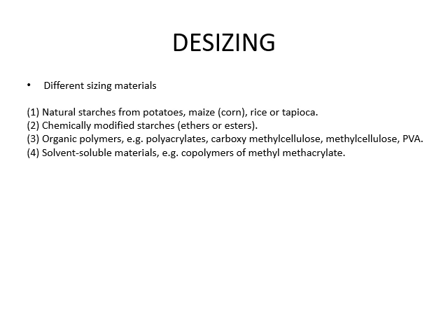Specifically, PVA is often captured from the desizing process and it can be recycled. The vegetable starches cannot be recycled, while the other synthetic sizing materials are not cost effective when recycled. This size removal also depends on those factors we will discuss.